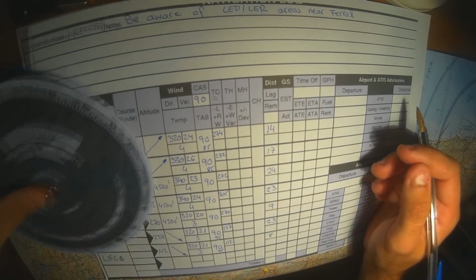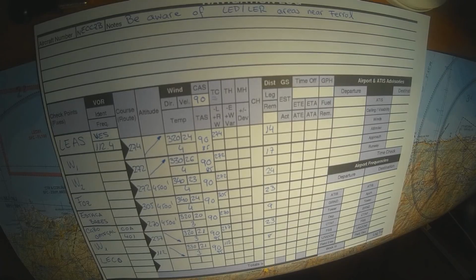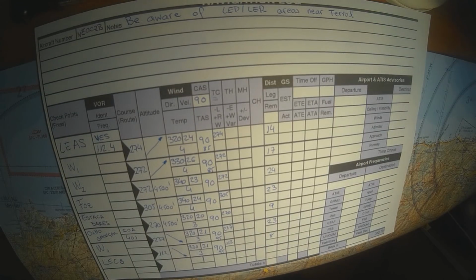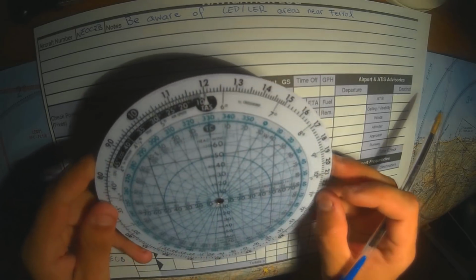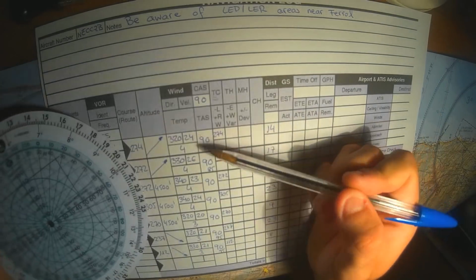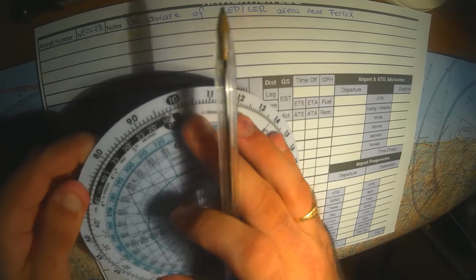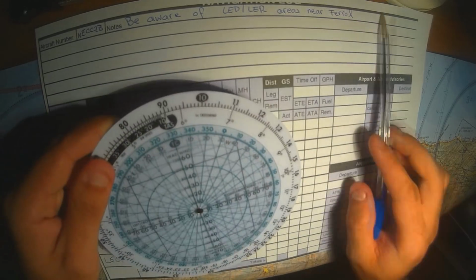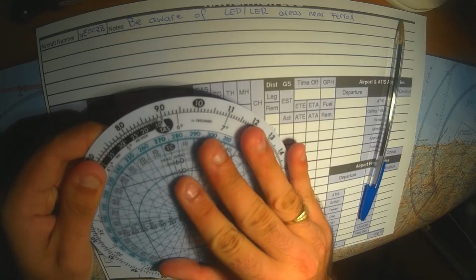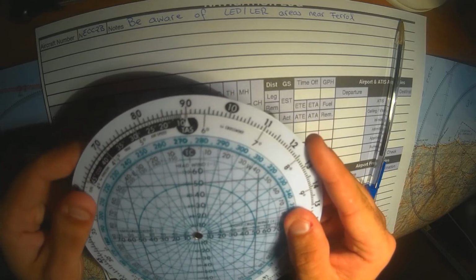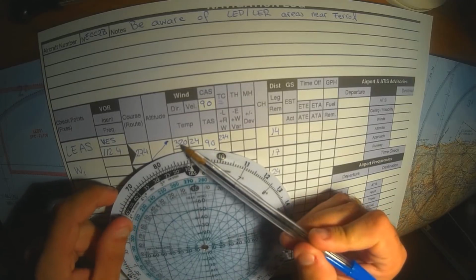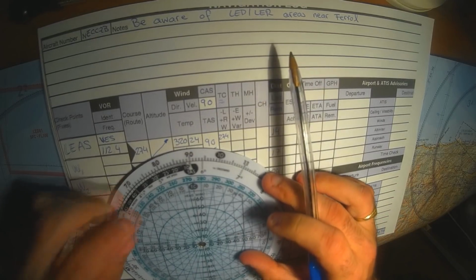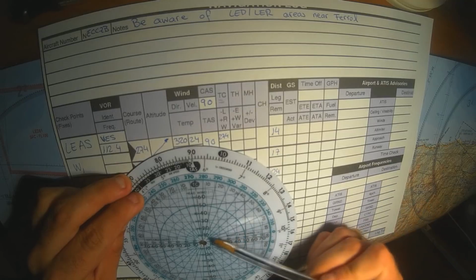Okay, let's determine how the wind is going to affect our flight. For this, the CR3 will again help us a lot by flipping it over and using the wind component face. The first thing we must do is align the TAS arrow with the numbers above. Be advised these numbers are represented in tenths, so 1-2 means 120 knots. We now rotate the inner disc and align our true course with the TC mark. Let's find our wind direction within the green circle and then the speed. Each of those inner green circles represents increments of 10 knots.